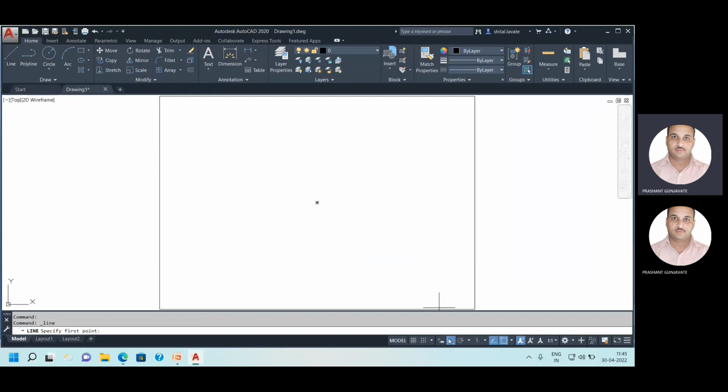I have made ortho mode on. I can draw a horizontal line of a certain length, let's say 50 mm. Just type 50. So how could I take this line command? First the line command L, specify the first point. While giving the second point, I will type 60 for 60 mm length. So this will be very easy. You can also draw a vertical line like this. But how could you draw a line with an exact angle of 30°?